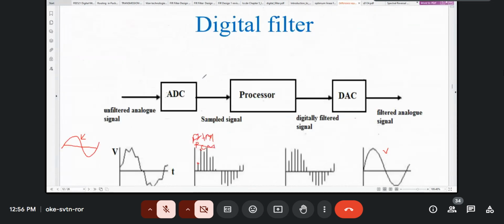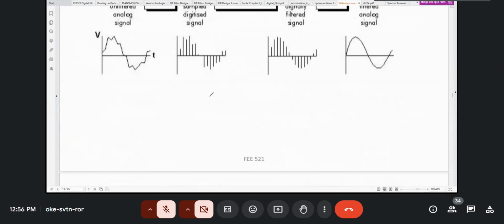In the scaling factor, of course, the coefficient can be negative or positive. The negative would mean it's going to affect certain frequencies negatively. It will kind of suppress them, and it will enhance certain frequencies when positive. Does it make sense? Yeah, that's what it would mean. Depending on the coefficient, the filter behaves differently. The filter will have different cutoff. We are going to see that when it comes to designing the filter.